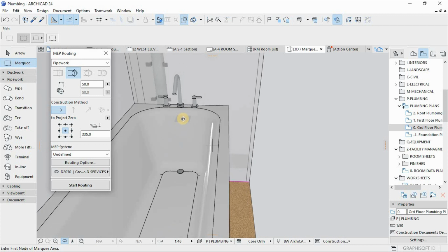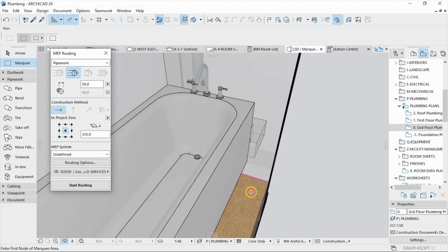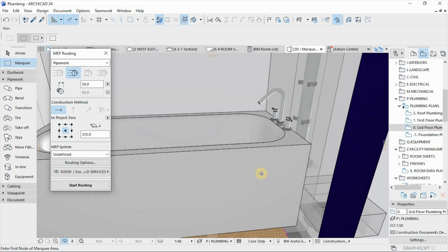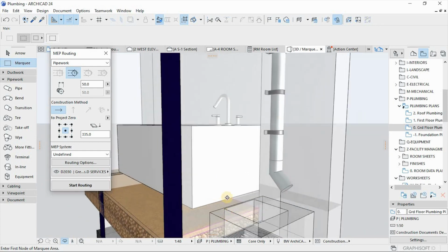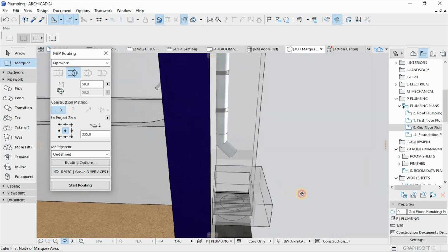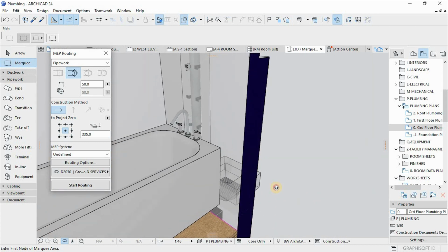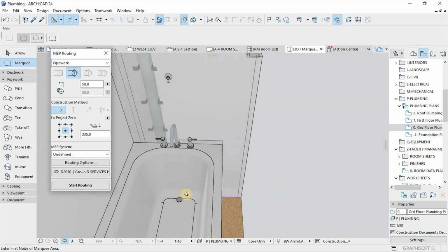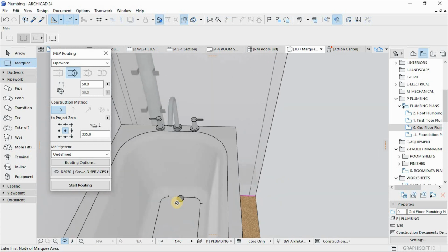The second part is the tap basket, which is the area that will be used to collect water to the gully trap. Another component is the S-trap, that is also part of the system that collects water from the tap basket. Let's get started. The first thing is to start with the tap basket here.